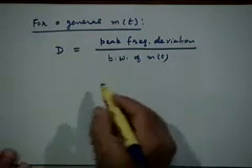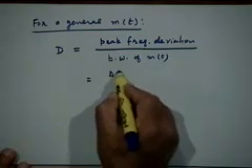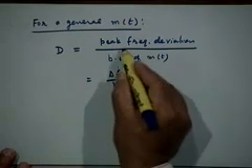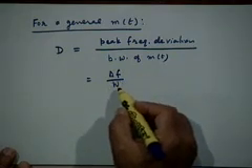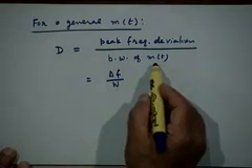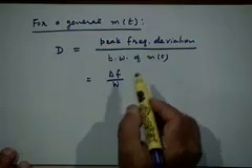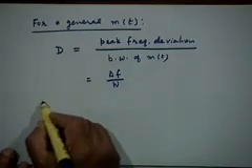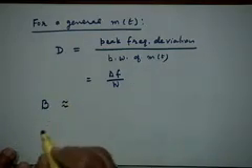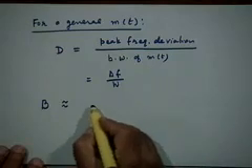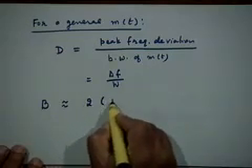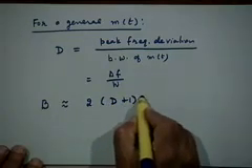So let me call this delta f upon W. Delta f is the peak frequency deviation of the FM signal or the PM signal. W is the bandwidth of the message signal m(t). Then it can be shown that approximately the 98% bandwidth of the FM or PM signal is now given by 2 into D plus 1 times W.